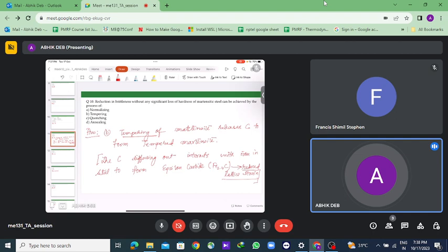Some of the carbon will diffuse out, not the entire carbon. So in those sections, this compound will be formed. So you cannot say that the tempered martensite has this composition. This epsilon carbide will be formed at certain specific locations where the composition will be Fe2.4C, and there the lattice strain will be reduced. Okay.